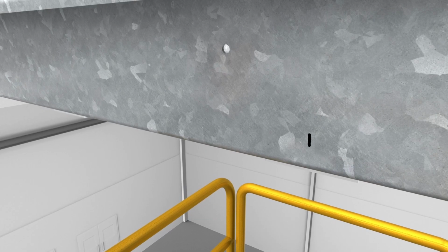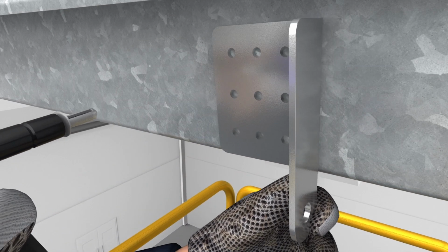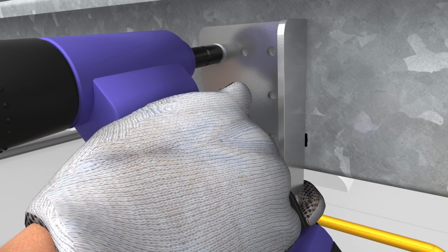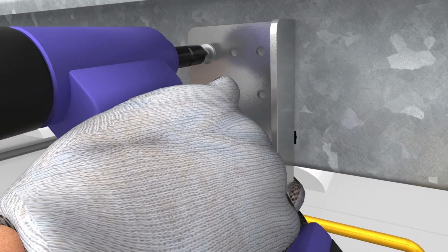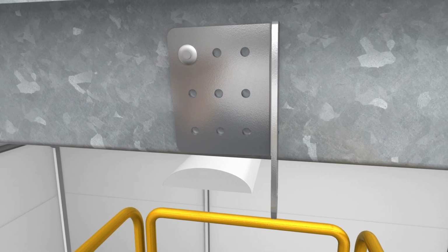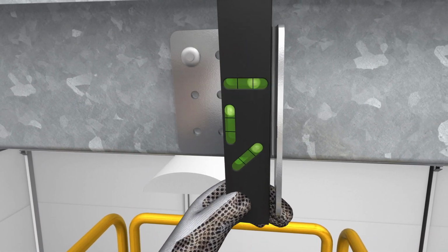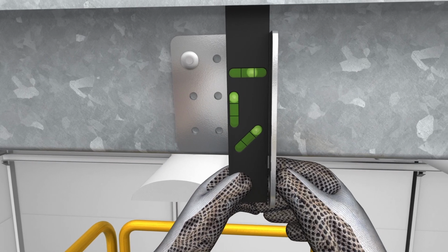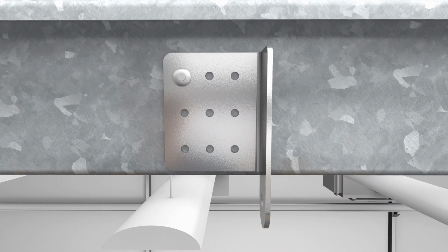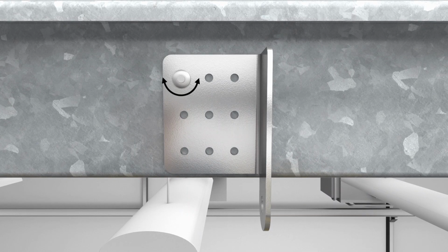Using an appropriate riveting tool, insert a 5/16 of an inch rivet into the corresponding fixing hole and secure the perpendicular purlin bracket into position. Prior to drilling and riveting the remaining fixings, using a spirit level, check the parallel purlin bracket is set at 90 degrees to the purlin. The single 5/16 of an inch rivet should have sufficient clamping force to minimize unintentional rotation during this process.